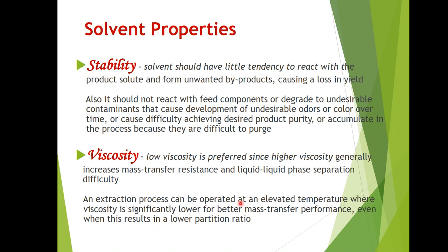Then we have viscosity. There should be low viscosity in extraction, since higher viscosity generally increases mass transfer resistance and liquid-liquid phase separation difficulty.